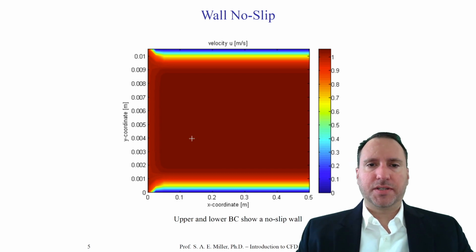Now, in some solvers, it can cause a huge problem to have a velocity inlet condition, like on the left, and a no-slip wall in adjoining parts of the domain. Sometimes this might crash the solver. We'll talk about a way to get around that next.